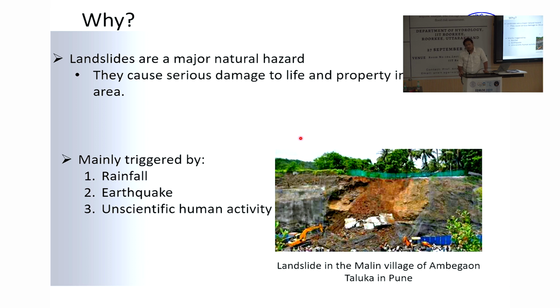The lithology of Himalaya is unfortunately very well suited to landslides. The rocks are highly deformed, and a lot of rocks have very fine grained structure, which makes slippage very easy. Plus, they have a high porosity and permeability, which allows seepage of water. So Himalaya is especially suitable for landslides. It's not just the bad construction or bad planning, but it's also geology that controls, because of which we have so many landslides in Himalaya.